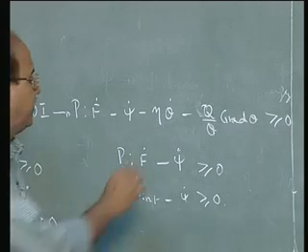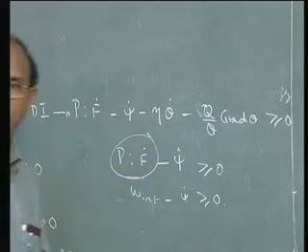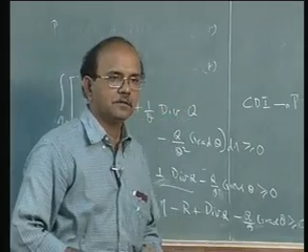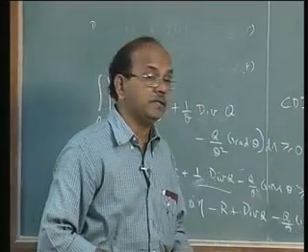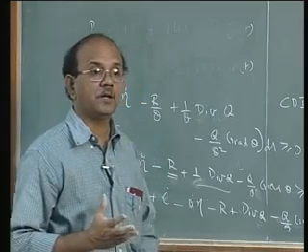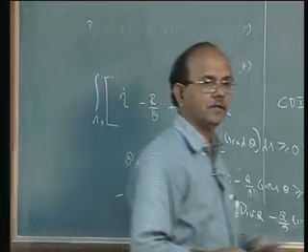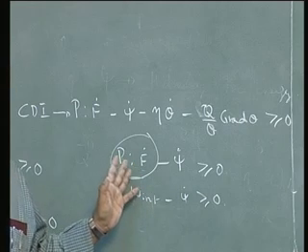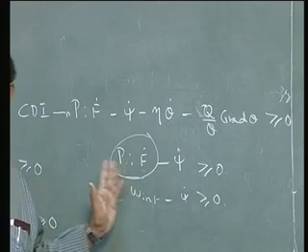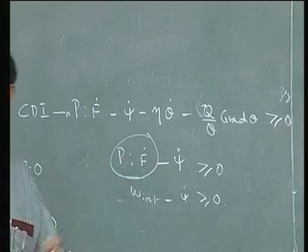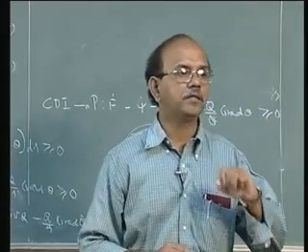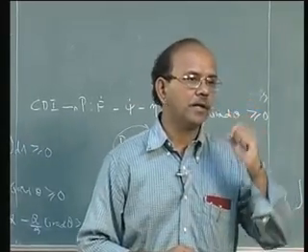Right. But look at this term. I just want to comment on this a minute before we move to the next topic. Please note that P, what is P? The first Piola-Kirchhoff stress is the work conjugate of F dot. So P and F dot go together. We had done that before. You have to look at this carefully as to what terms you use in your analysis.